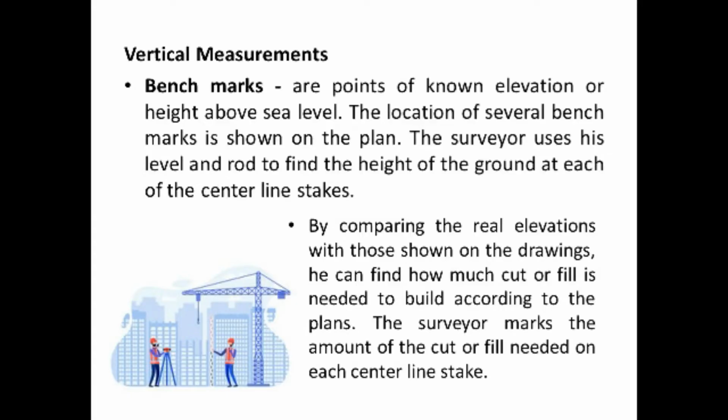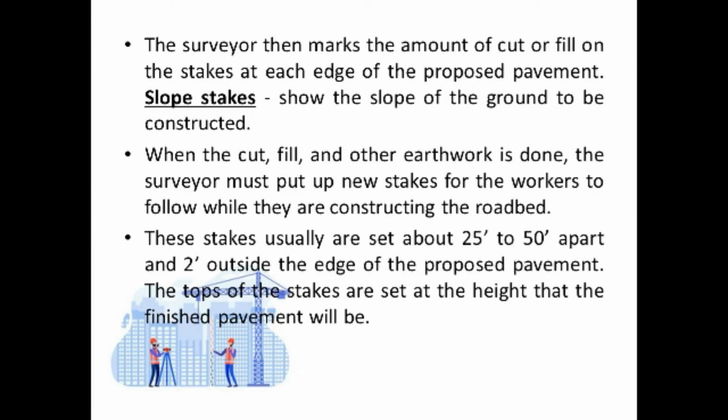Then, the surveyor marks the amount of cut or fill needed on each center line stake. After this, the surveyor then marks the amount of cut or fill on the stakes at each edge of the proposed pavement. The cut or fill should slope from these stakes to some point on the ground.